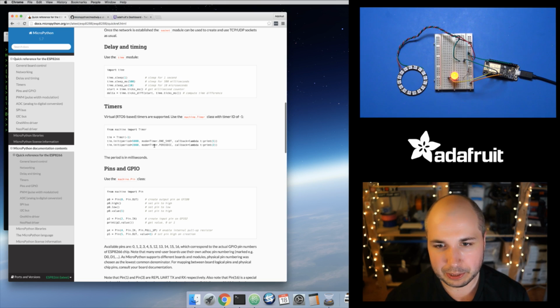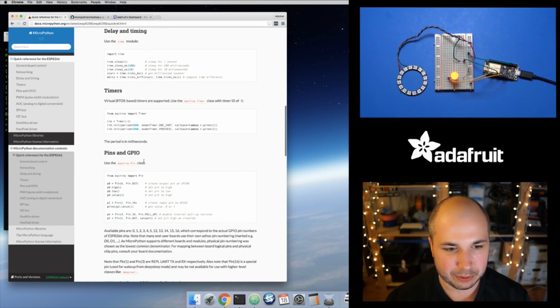And that's another thing, you've got one core, and so you've got to make the most use of it. You don't have threads. There's not a full operating system in here with a kernel and context switching and stuff like that. So at least the Python code doesn't expose anything like a thread to go run a task in the background. So a timer is kind of like a poor man's thread in some way: if you want something to happen in the background, quote unquote, you could run a timer that will kick at some frequency and run some of your logic for that. So good to know about that.